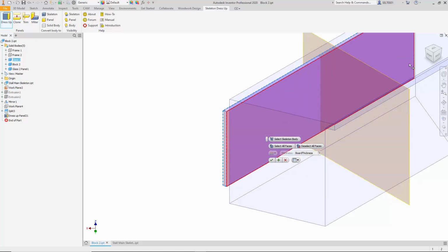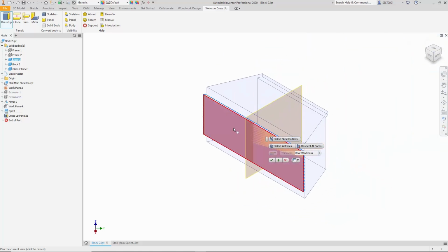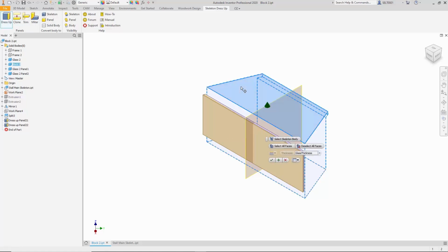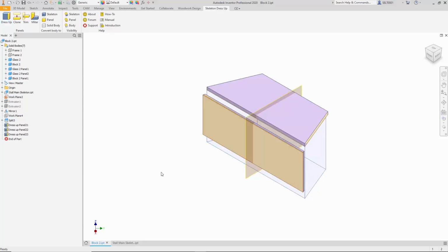As we can see, the plate has been produced, and the next step is to create the glass. Selecting another plane, this time it will be produced outward. We also determine the parameter that specifies the thickness of the glass. Next, a countertop is needed. For the countertop, we specify the surface on which it will be supported and the direction in which it will go inward. We also select the parameter that determines the thickness of the countertop plate. Just like that, we have constructed these non-standard components.